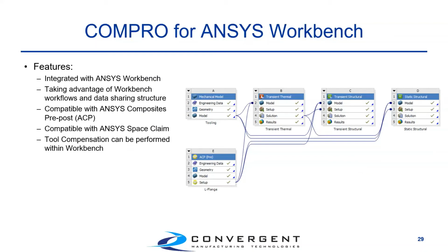As I said, it's compatible with the ANSYS Composite Pre-Post, ACP, as well as SpaceClaim in ANSYS. And you can perform the tool compensation within the Workbench framework as well. You can bring back the deformed geometry, and if you have the geometry definition within the Workbench, you can compensate for it within the Workbench as well. So everything can be done within the Workbench framework.